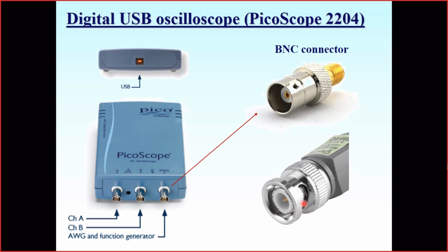You put a plug over the socket, turn this lock, and you get a connection that couldn't be so easily disconnected. So be careful when you disconnect it. Don't just pull. You have to turn the lock first to open the connector and then remove the plug from the socket. So the BNC connector is one of the golden standard connectors for high frequency signals.